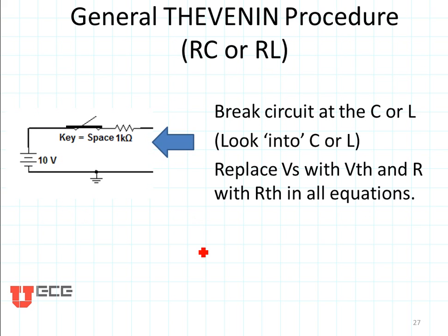Now let's consider a general Thevenin solution procedure. In this case, we break the circuit where we are looking at the capacitance or inductance, and we look into the circuit. And then we go back to the equations I just gave you and replace Vs with V Thevenin and replace R with R Thevenin in all of the equations.